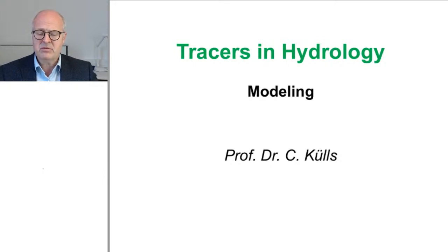Now yesterday I gave you 3 cases. You want to carry out a tracer test to study the interaction between the swamp and groundwater. A river flows into the swamp and no river leaves it. So basically the outflow occurs either by evaporation, which is unlikely, or by seepage. You have a borehole downstream of the swamp, so actually you measure in the groundwater. Please describe the test prior to the experiment. Choose one or more tracers and justify your choice.